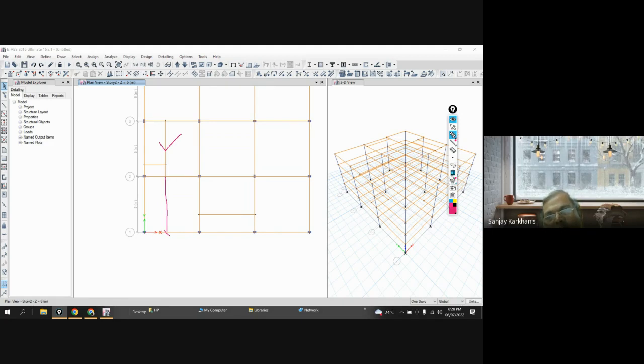See, there are facilities, but which facility you should use depends on if you start thinking what you want and what you have. Only then you can do that. So I know that I want this beam to be extended up to this. So I will select that beam up to which the beam is to be extended. Then I will select the beam to be extended, and then I will select the joint to be extended. Process clear? Yes, sir.